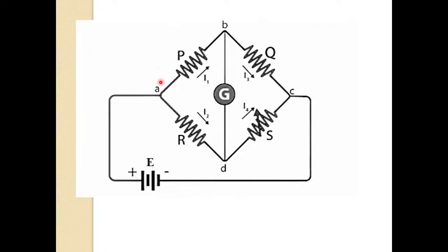So this Wheatstone bridge consists of two known resistors, one unknown resistor and one variable resistor connected in the bridge. Here, there is a variable mark on S. This variable mark on S represents that this is our variable resistance. R is our unknown resistance. P and Q are known resistors. And this is a very reliable bridge as it gives accurate measurement.